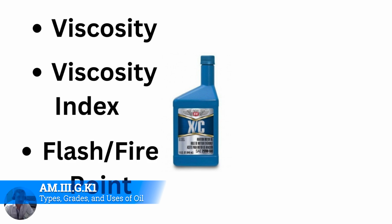Okay, let's talk about the flash and fire point. Flash point is the point where the oil will start to give off gas that can be ignited, so it'll flash, but it won't be sustained. Fire point is when it's hot enough to continuously put off that gas to burn and actually be a sustained fire. Most of the time, if you see engine oil on fire, it's going to have to be above that fire point, because the oil itself won't necessarily burn, but what comes off of the oil will be burning. And you'll see that.